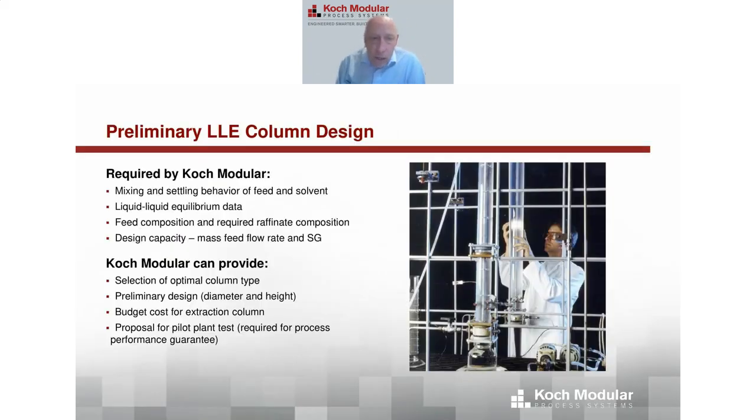Okay, so before I turn this over to Brendan for this last part on pilot testing, I just want to conclude by saying, if you come to Koch Modular and you want to know something about what a column will cost and what the design would look like before pilot testing, what we need is the mixing and settling behavior of your feed and solvent. We need your equilibrium data.